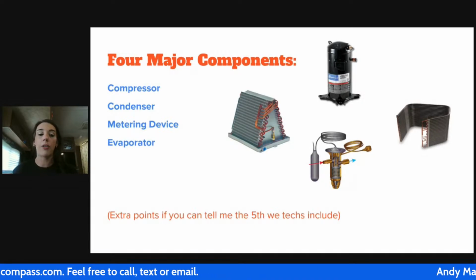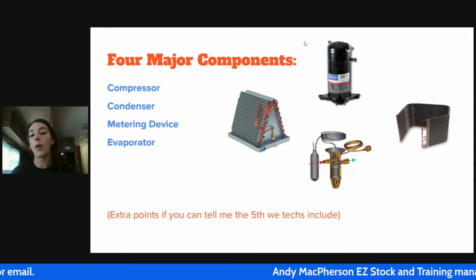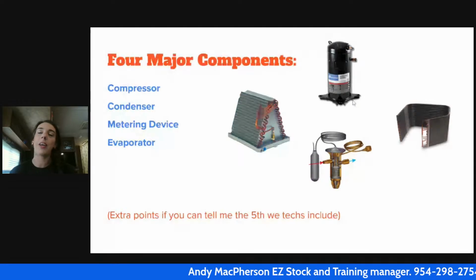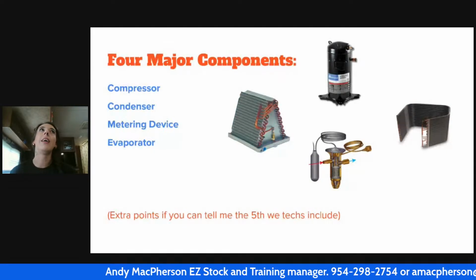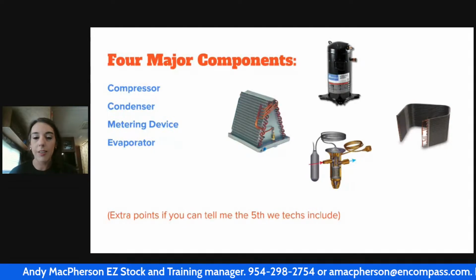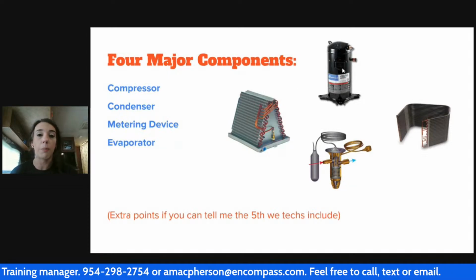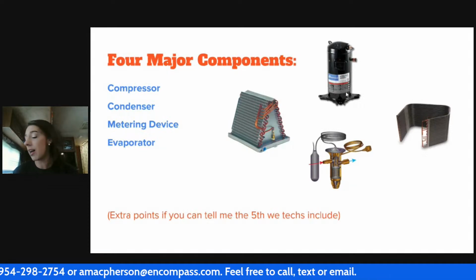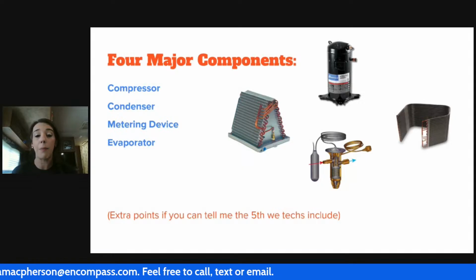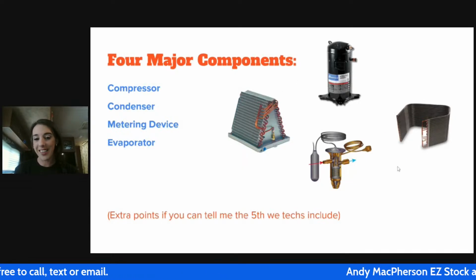Some people are under the misunderstanding that a compressor is a pump of some sort, or they'll call it the motor. And when we call it things like a pump and a motor, it removes what it actually is. It takes away the actual job, the thermodynamic work that the compressor does. It compresses. It does not pump. So therefore, it has to have vapor only. So those are the 4 main components. The 5th, you guys, is a thermostat.